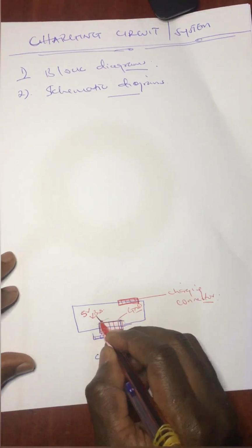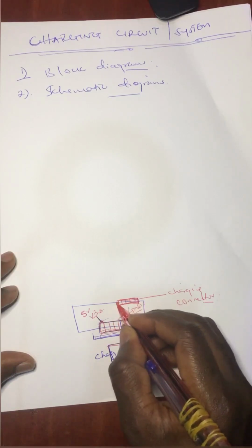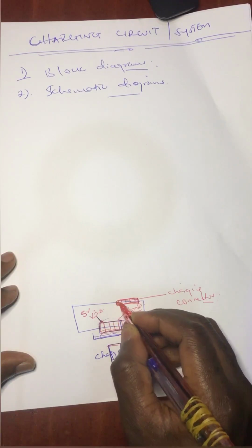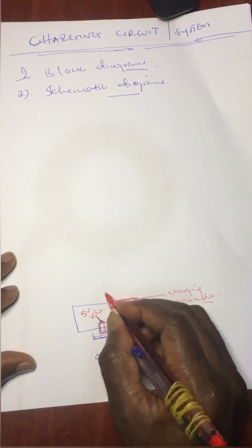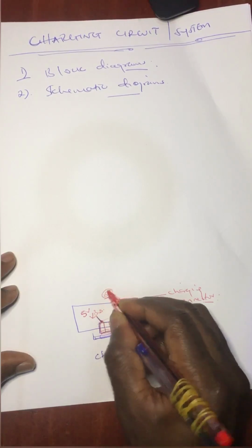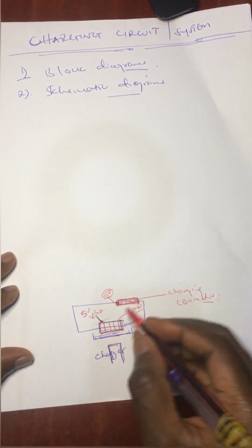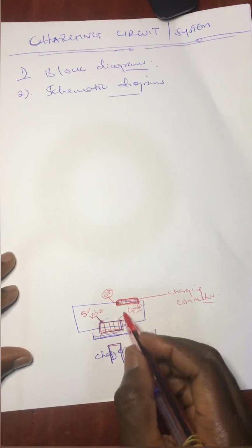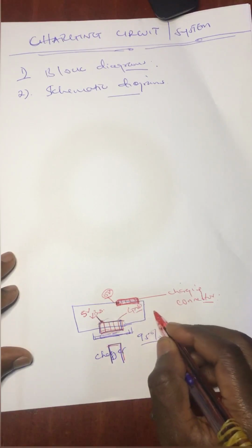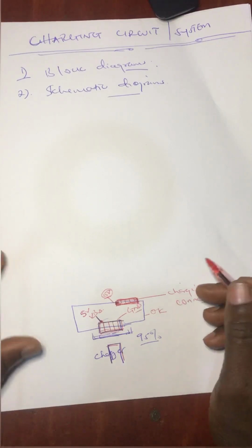After this, the charging board delivers the 5 volts right here on the charging flex connector. So you also have 5 volts right here, on the connector for the charging flex. The moment you have 5 volts right here, it also means that your charging board is okay. So where else do we go to?